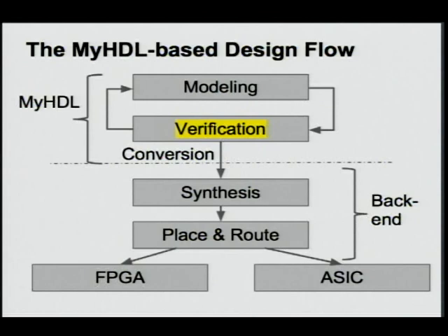But let's first discuss a little bit this design flow. So what you have here is a modeling phase where you write your code, and then you have verification with test benches and all kinds of stuff, and you iterate until everything works. This is like you would do in software, right? After that, when you're finished, you convert the RTL code, and you go to synthesis, place and route, etc. Okay? So this is globally how you design a hardware system in MyHDL. Now, let's talk about verification in more detail.